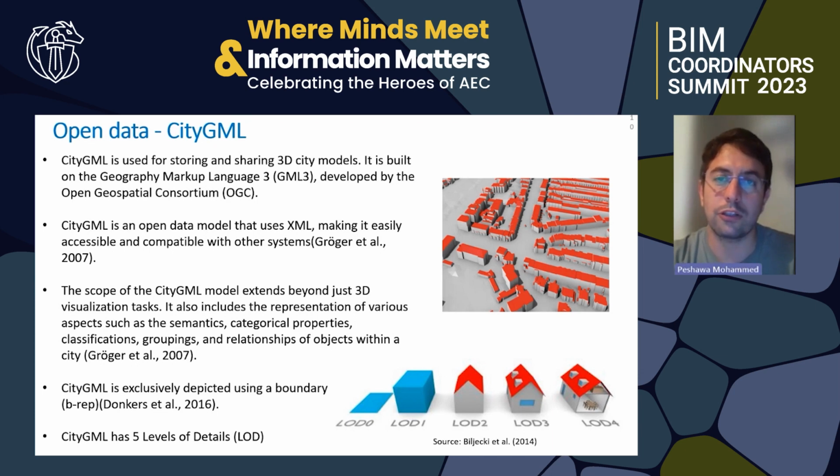And it's worth mentioning that CityGML is not about just 3D visualization, but also semantics and categorical properties and relationships between objects can be stored and transferred using CityGML as well. CityGML is exclusively depicted using a boundary representation, B-Rep, and it has 5 levels of detail.